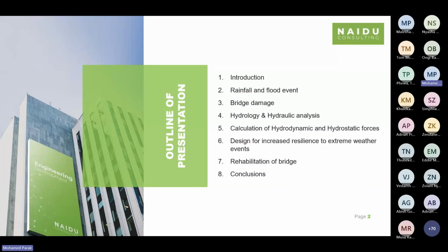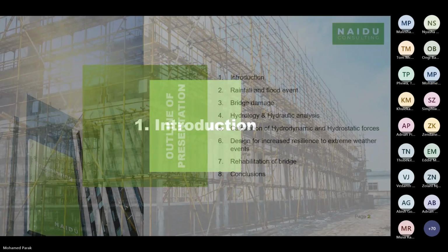My presentation this afternoon will encompass the following. I'll start off by looking at the rainfall and flood event that caused the damage to the bridge. We then analyze the magnitude of the flood event and calculate the hydrodynamic and hydrostatic forces that caused the damage. I will then describe the rehabilitation measures undertaken to restore the bridge, including the adaptation measures retrofitted to the bridge for increased resilience for extreme weather events, before concluding with the presentation.